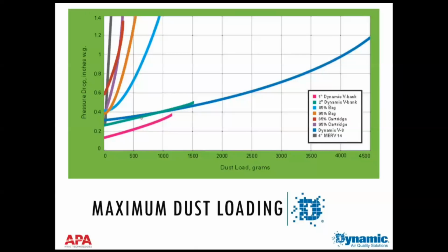This is a graph of dust holding versus pressure drop. And so switching back to my laser pointer, this is dust held going to 1.4 inches, which is the, quote unquote, final static in the ASHRAE 52 test.